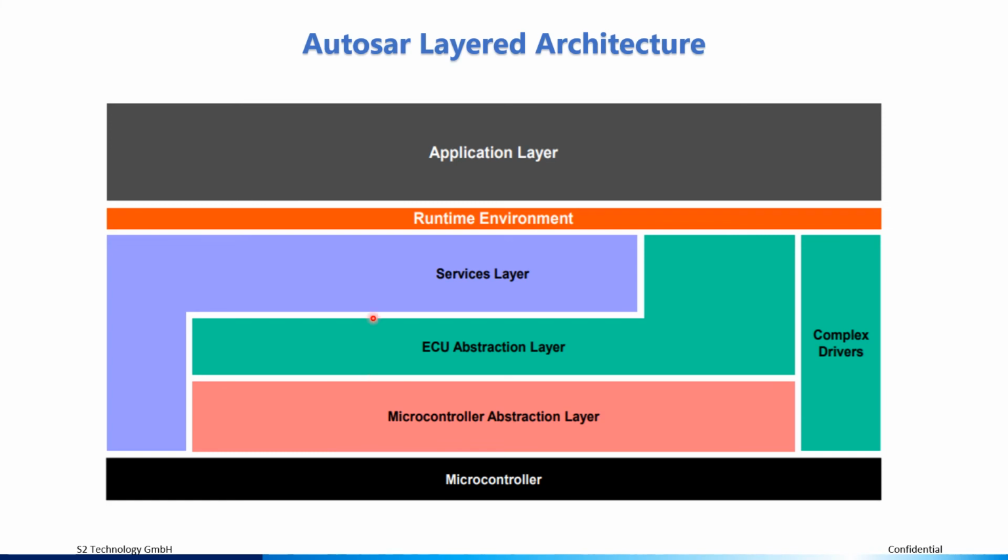Then we have the ECU abstraction layer, which interfaces the drivers of the microcontroller abstraction layer. It also contains external drivers. So this ECU abstraction layer enables that one application will not be coupled with certain ECUs. This ECU abstraction layer gives that benefit.